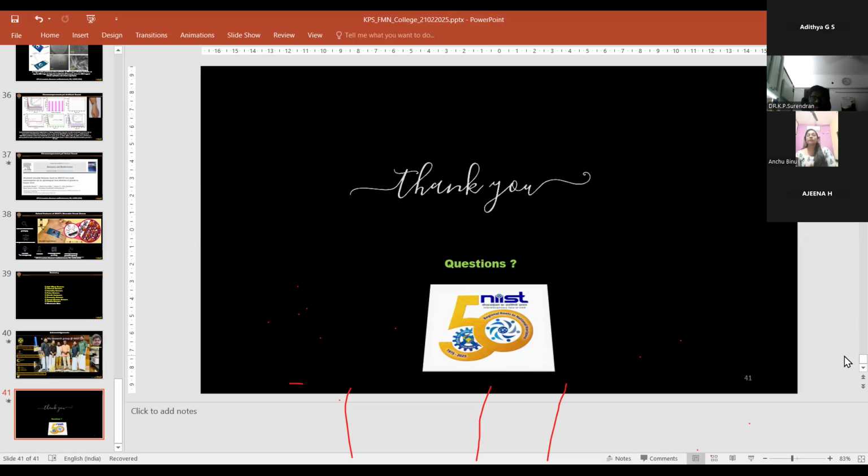But when you are making a wearable piezoelectric sensor, it should be composited with a polymer, and the polymer will not be stable at high temperature. So a high temperature piezoelectric wearable sensor is always limited by the melting or temperature deformation of the polymer. If you are using PVDF, the maximum you can go is maybe 200 degrees, beyond which the polymer will degrade in a big way.